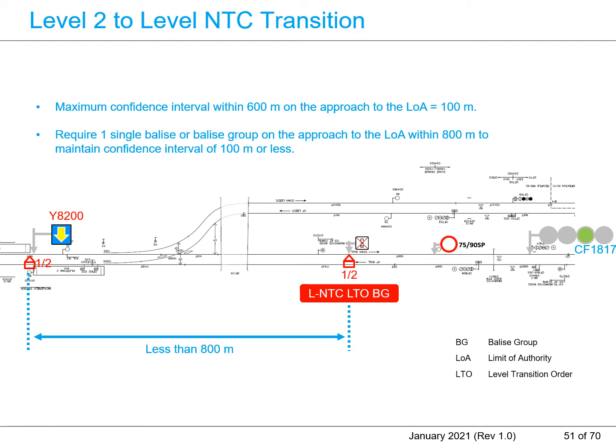The Balise group for RSPY8200 is within 800 meters distance on the approach side of the LOA. Therefore, additional Balise for resetting the confidence interval is not essential for this layout.